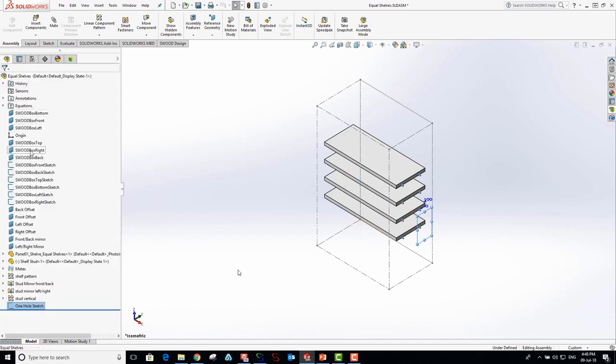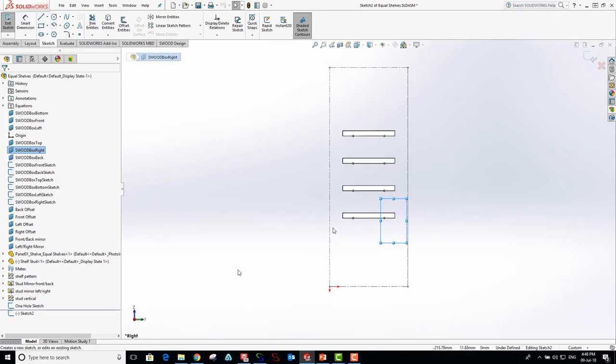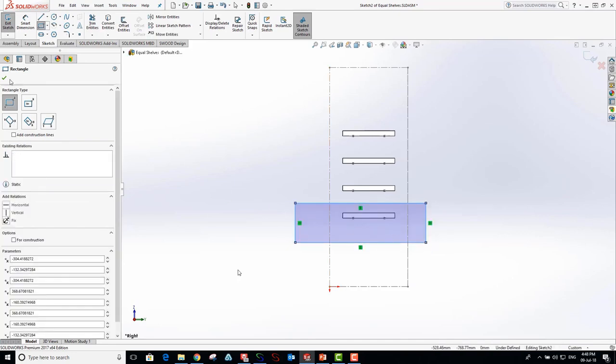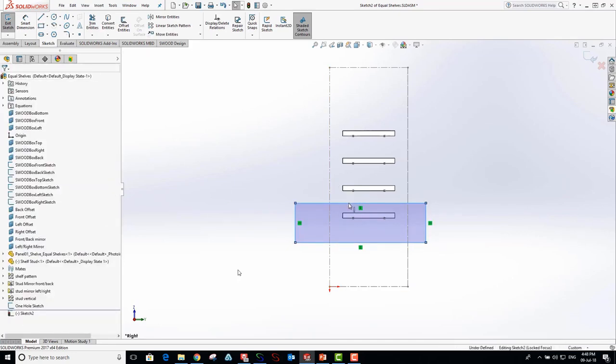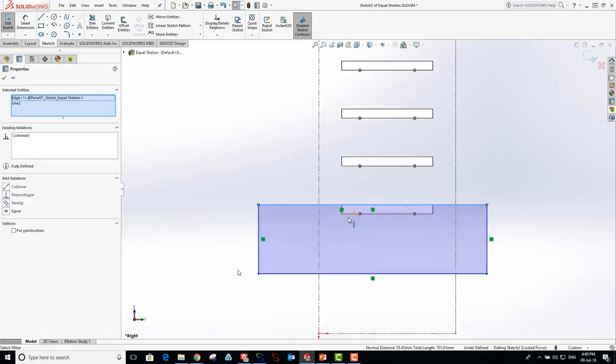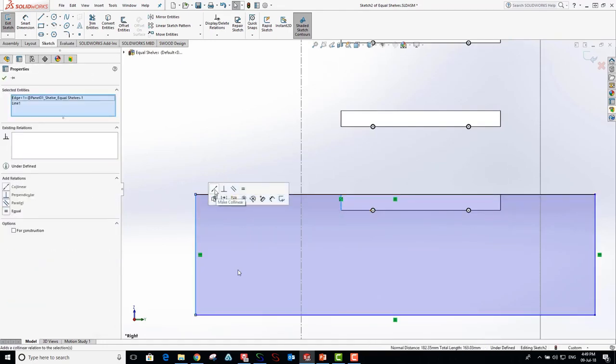Now, having defined one parameter for the one hole sketch, what we'll look to do is replicate that for each and every type of option that we want, whether it's the 3 holes per shelves, the row of holes, or in this case we're going to work through the example of the rebated shelf. So in this case it's not a circular machine defined hole that we want, it's a rectangular cut to be positioned in the sideboard of the frame.